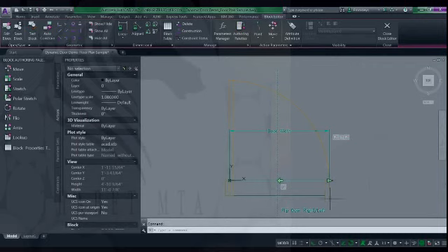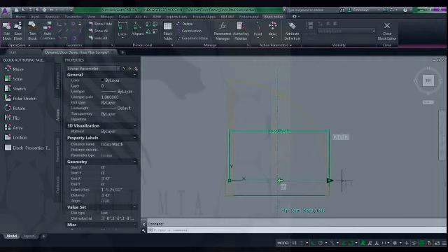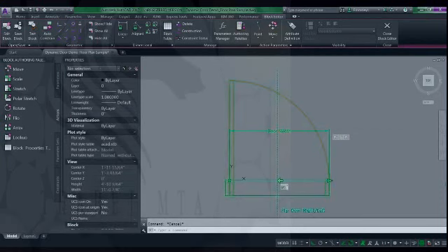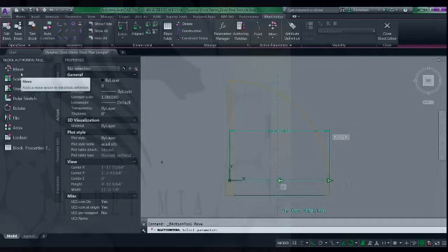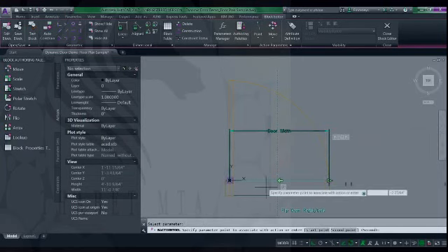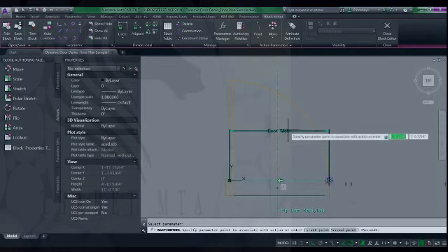So it's good. So it's working. Everything is associated: my flip command to my action commands, my actions, and my parameters that I made previously. So let's go ahead and assign our midpoint to actually move when we stretch our door. So I am going to need to come in to my actions on my palette and select move. And I am going to go ahead and select my original parameter, because I want my midpoint to stay with me no matter how far I stretch it. So I'm going to select my original parameter. Then I'm going to select my endpoint here.